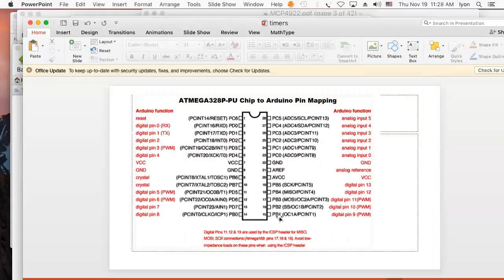Well, that's also on port B. And see how it says port B0 and port B1? Well, that's kind of important, right? Because you're going to be writing to the B register if you're going to write these things directly instead of one pin at a time. So you can set them both to 1, 1, or you can set the least significant bits to 0, 0, or whatever you like. And that's going to essentially allow you to manipulate this port B.